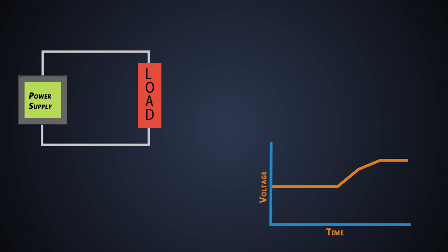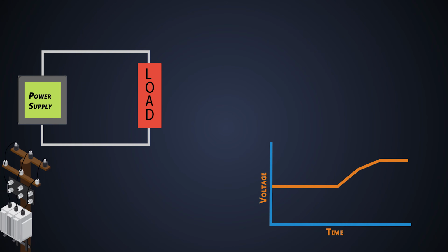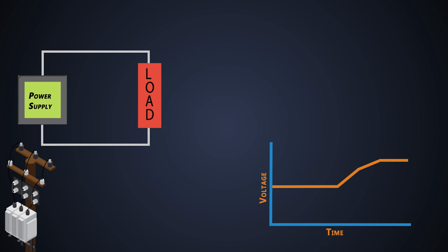An overvoltage condition might occur in the power supply due to faults inside the supply or from external causes such as surge in the power supply lines. In this protection, we have to set a threshold voltage above which the control circuit shuts down the supply or diverts the extra voltage to other parts of the circuit. And we can use BJTs to protect any circuit from overvoltage. This is the most important application where BJTs are widely used.